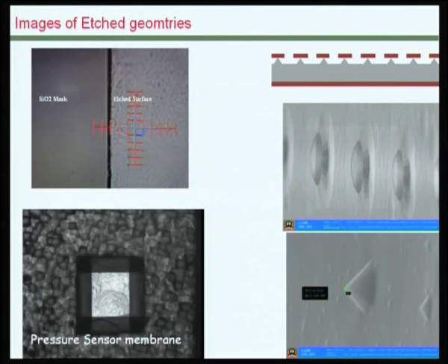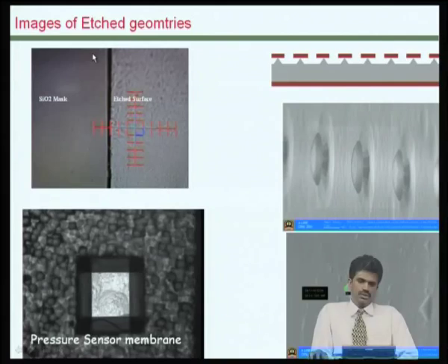So, we can do this by etching from the other side, and by having these regular side walls, which is a feature of anisotropic etching, we can have a predictable surface for the cavity. As you could see from here, the etched surface is inclined with respect to the silicon dioxide mask, which is largely unaffected in many practical situations.